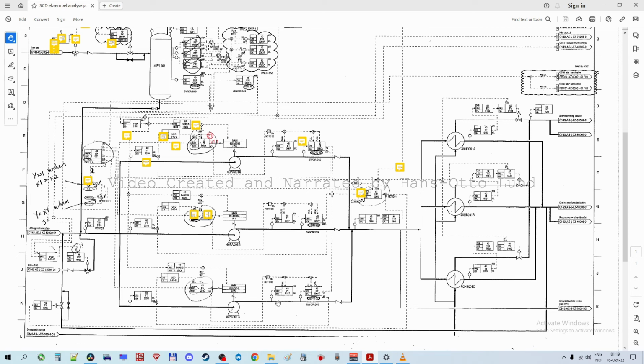On the outlet you have something which watches out for the flow. You need to make sure that you get a flow through the system. So you have this transmitter here, which measures the flow, and the function of this particular one is that it measures if the flow is getting a little bit too low, and then it warns about that.